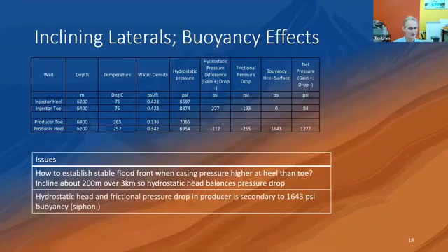The other thing to look at is buoyancy effects. They're pretty substantial. Certainly in our case, we're at 6,500 meters. Then there are pressure drops down, so we incline the pipe to try and equalize the pressure across all the perforations in the lateral. Otherwise, what happens is you get preferential movement into the heel of the well, and therefore you get an unstable flood front. And the most important thing when you're doing geothermal production from laterals is that you stabilize the flood front, so you sweep the whole of the, in our case, 3-kilometer area rather than just the first half of it.